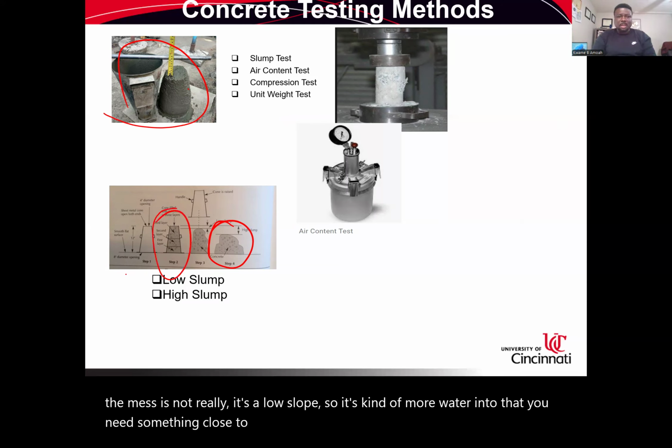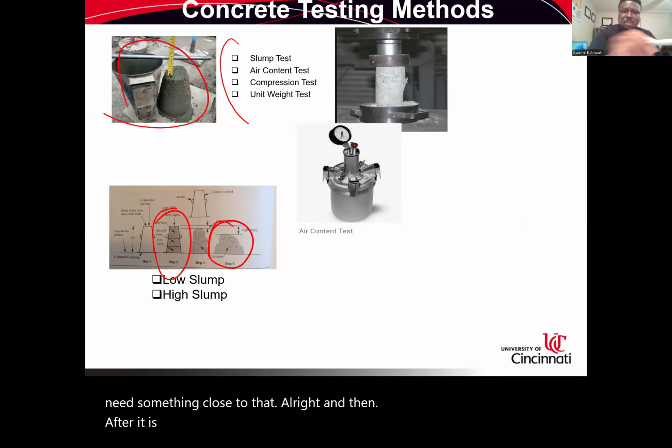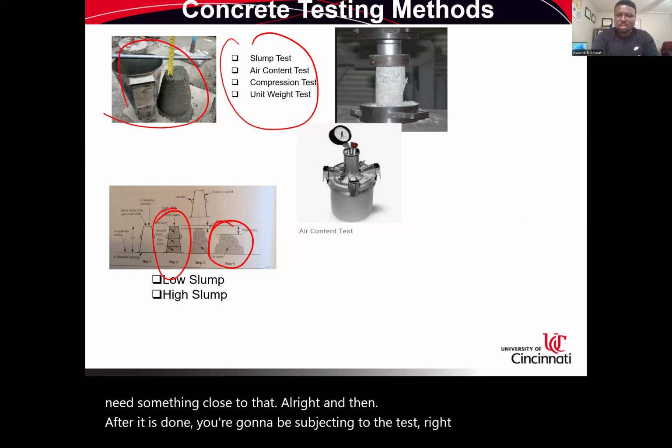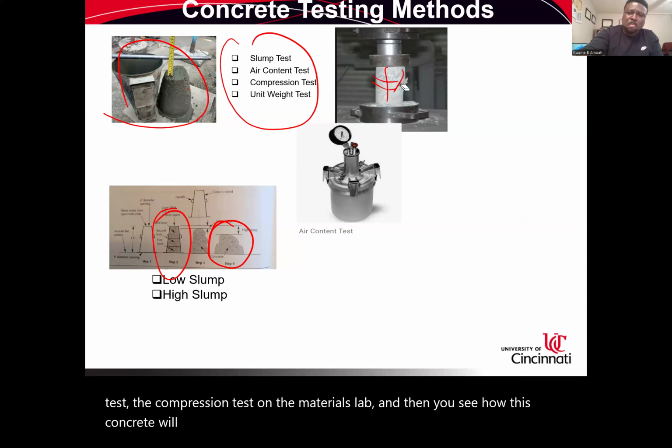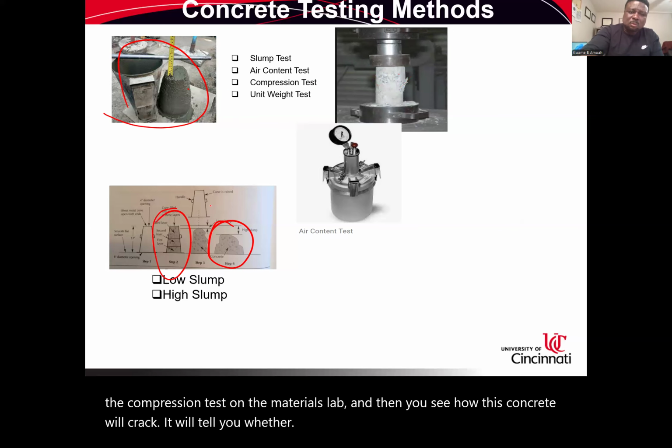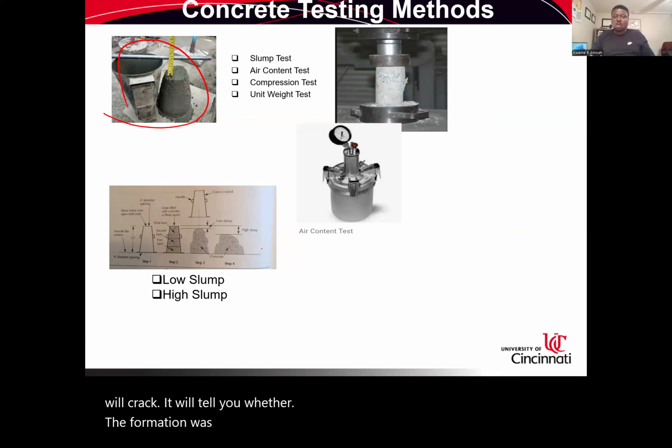All right. And then after it is done, you're going to be subjecting this to tests, right? The air content test, the compression test in the materials lab. And then you see how this concrete will crack. It will tell you whether the formulation was right or not.